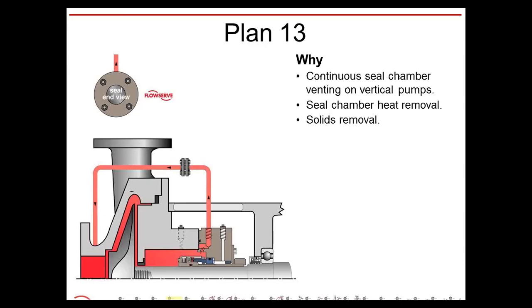Seal chamber heat removal, just like the Plan 11. And an interesting thing that the Plan 13 does is solids removal. Now, this is one thing I want you to note. If you have an application that has some moderate solids, the Plan 13 is an excellent way to remove them.